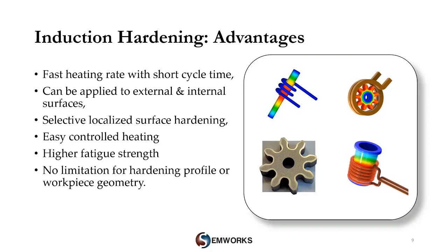It can be applied to external as well as internal surfaces, and it allows well-selected localized surface hardening by creating higher residual local stresses without affecting the rest of the part. It helps to get an easily controlled heating where the heated parts have higher fatigue strength without any limitation of hardening profile or workpiece geometry.